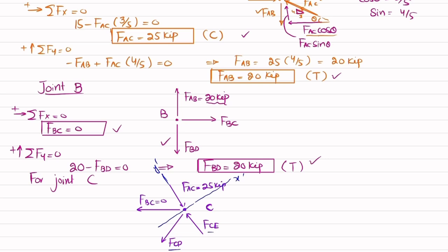So what we will do is first find the sum of all forces along x dash direction, which must be equal to 0, and force in this direction is taken as positive. So let this be making angle theta. So it will have 2 components, one is this one, and the other one is this one. So this component will be equal to FCD cos of theta. So I will write FCD cos of theta, and there is no other force along x direction. Clear? So it means that this is equal to 0. So it means FCD is equal to 0.